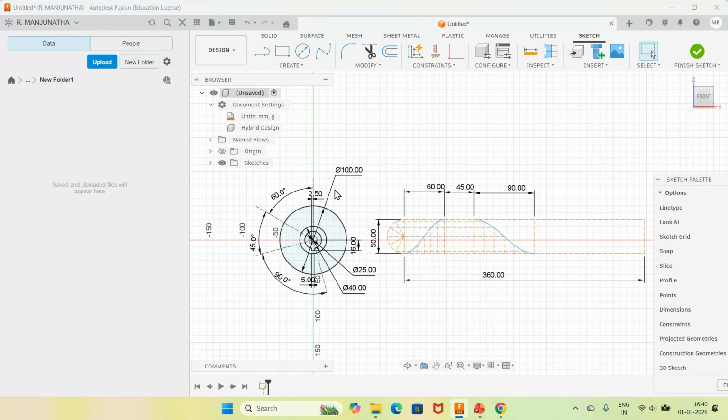So this is the one what I require. Once you do that, now I need to go for the further. So that means the vertical position will be the 0 degree here, what we are considering. That is at the base circle, the follower will be at this particular point. So from here, the outstroke is 60 degrees. So I want the outstroke of this 60 to be here.